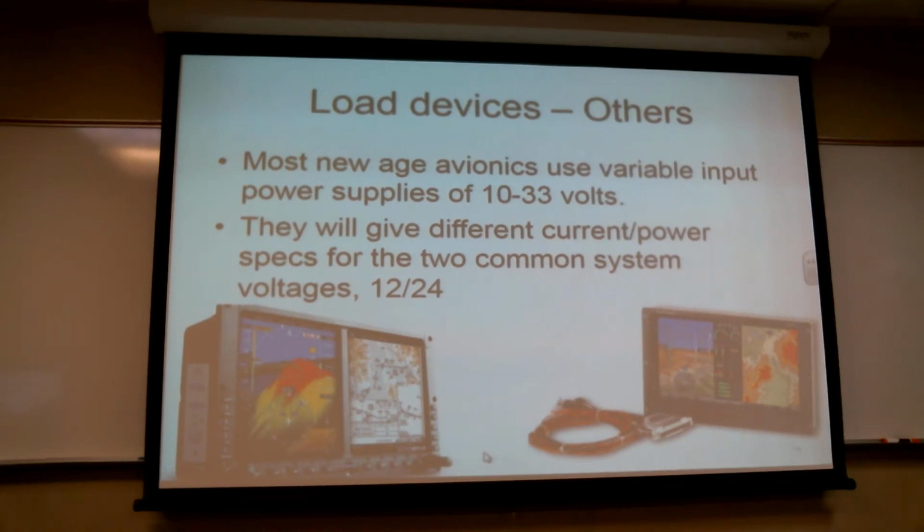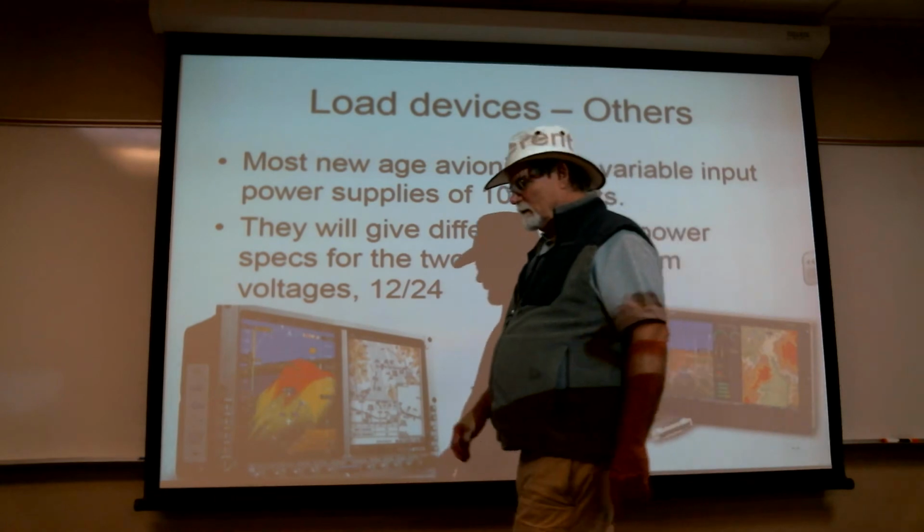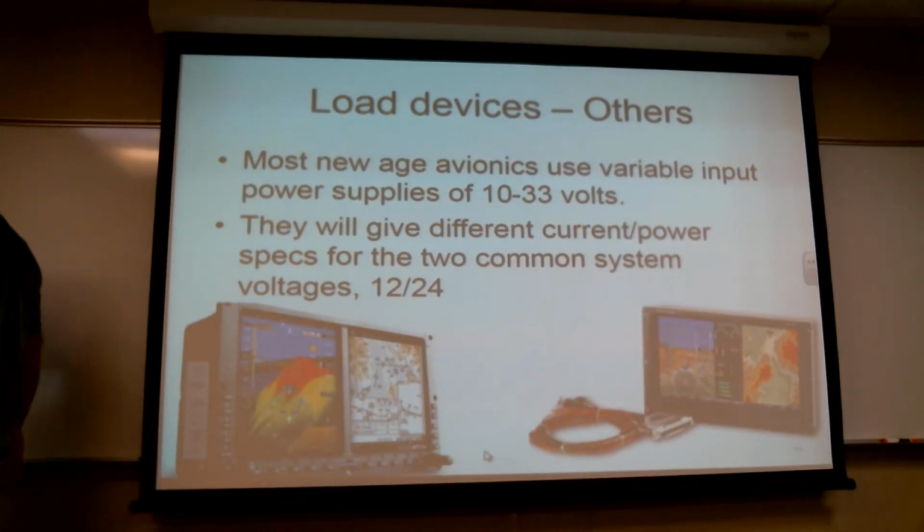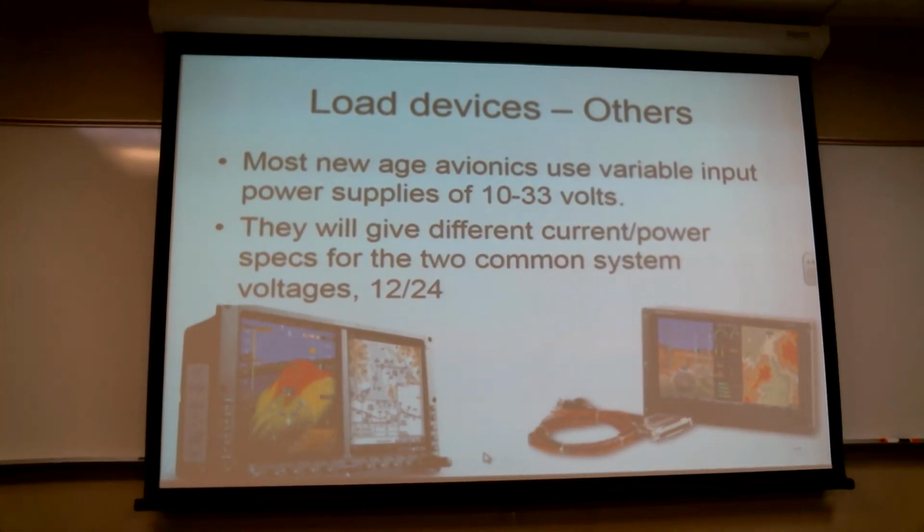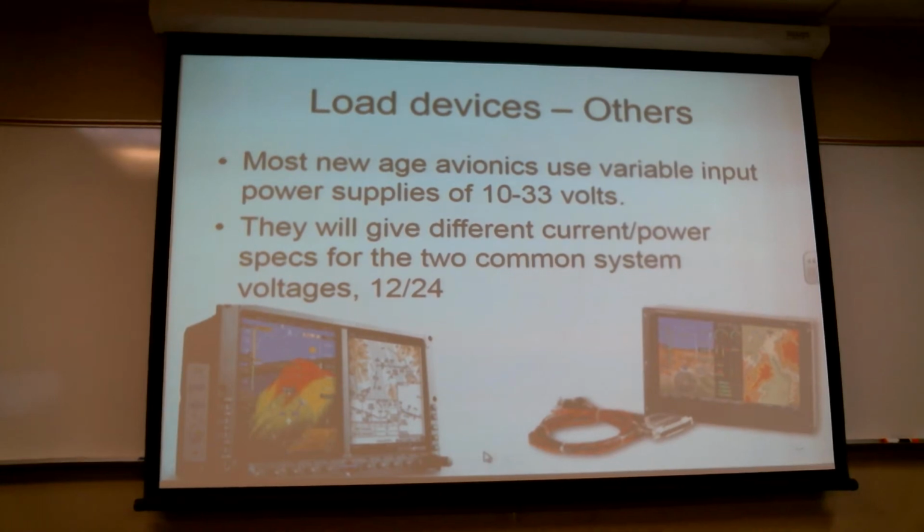Now, in the case of aviation, we really only have 2 input voltages for our basic DC stuff, 12 volts and 24 volts. Even the big airliners, 737s, etc., they have a 24-volt bus. They also have the 110 volt or 115 volt bus, but their starters run, if they run, well, I know 737s use a 24-volt starter.